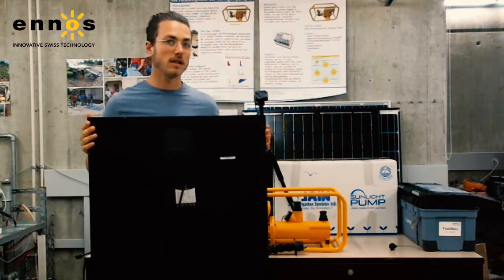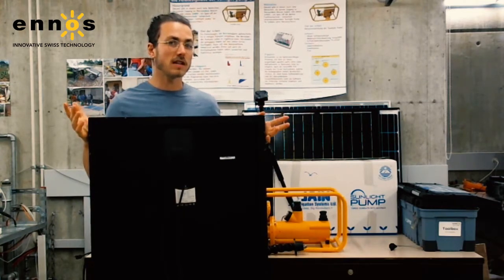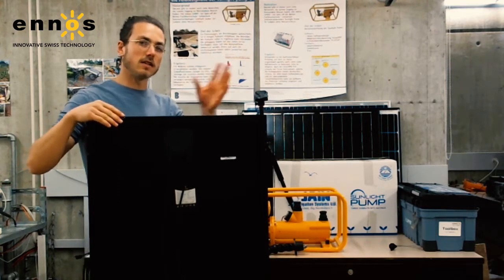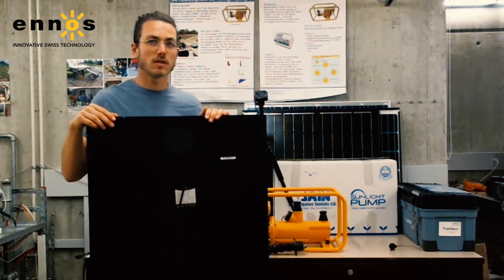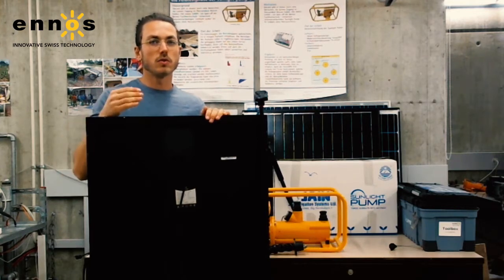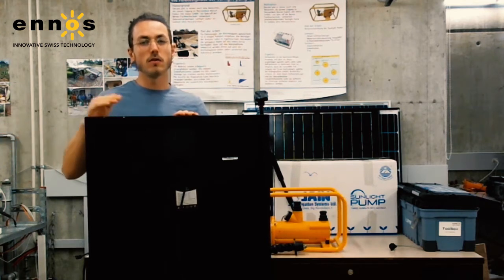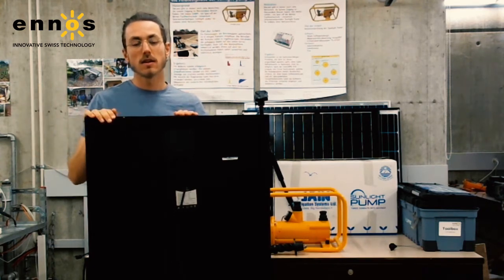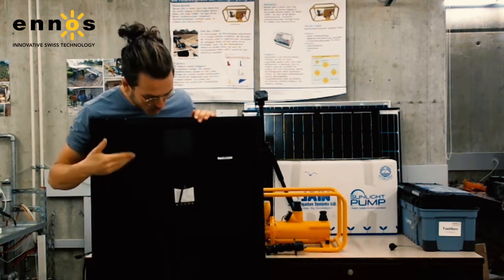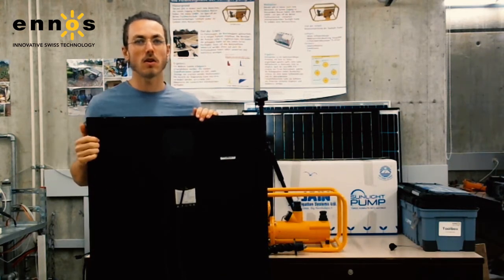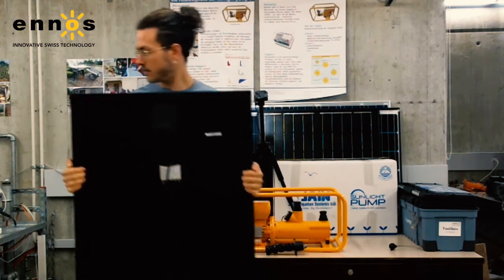This means this solar panel is perfectly fit for the sunlight pump, because it's in this range of 17 to 65 volts. If we were to set this panel in series with another panel, the voltage would increase. So we need to add the open circuit voltage of each panel to the next. So with 2 panels here, we'd be at 43 volts open circuit voltage, which is still within the capacity of the sunlight pump.